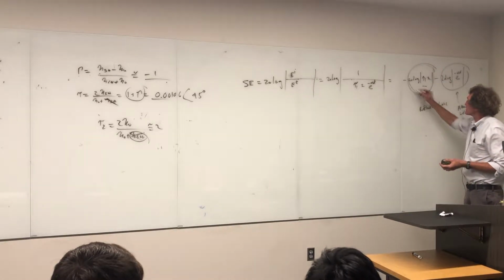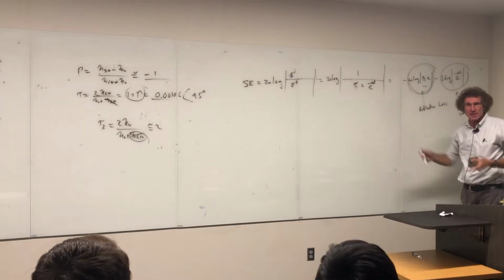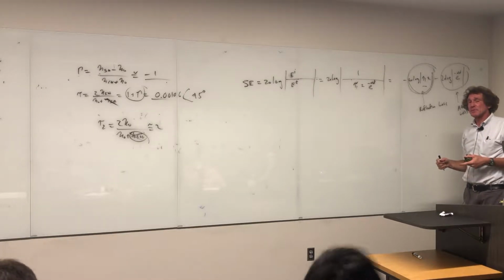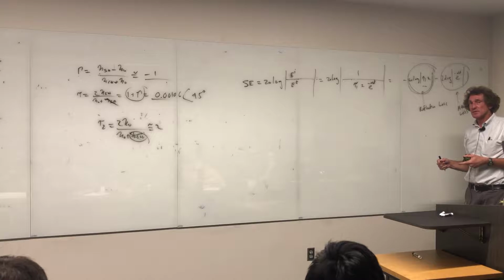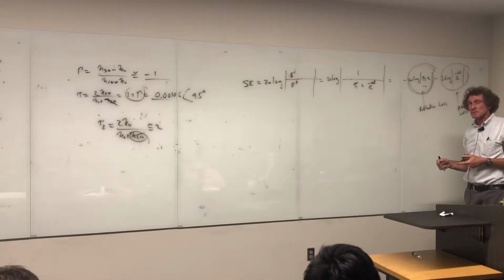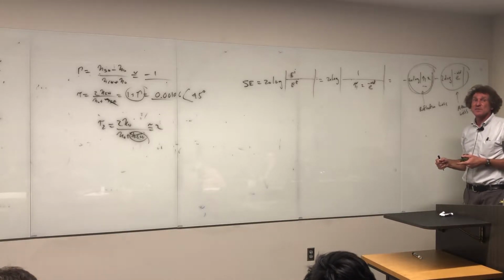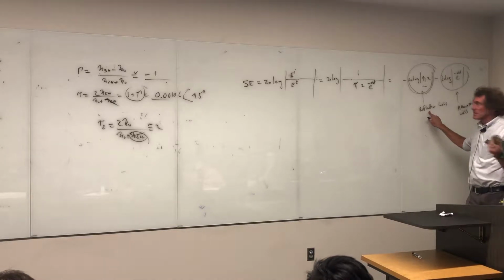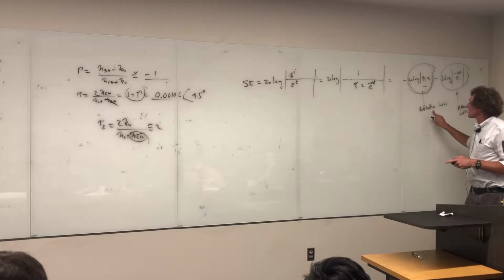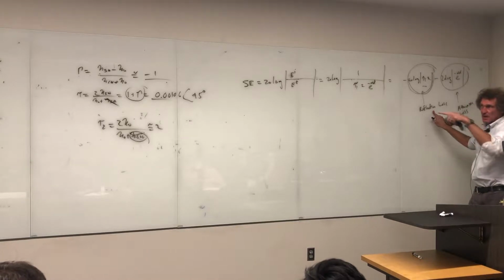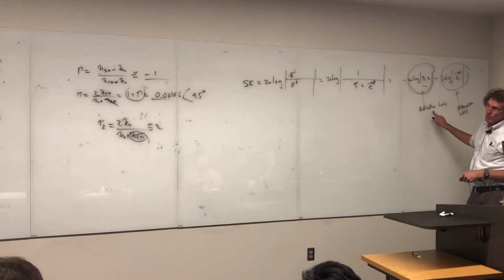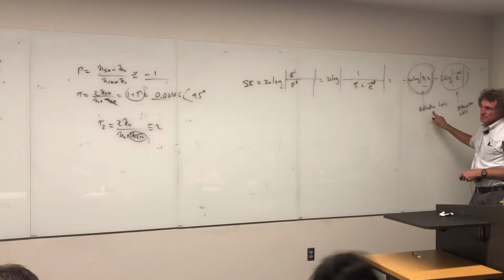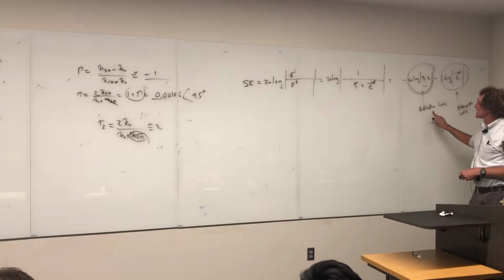This is a reflective loss, because did this problem ask for that or not? The next problem. Is it the same setup at 30 megahertz steel? 20 mil steel, yeah, 30 megahertz. All right, well, this is going to be the same answer for this part, because the thickness, 20 mils, goes here. But right now, what do you get for this for reflected loss? Just take that tau 1 that you had, 0.00106 times 2, that's a magnitude, and then take the log of it,